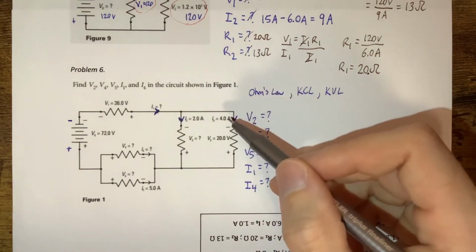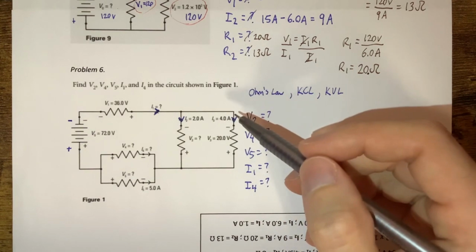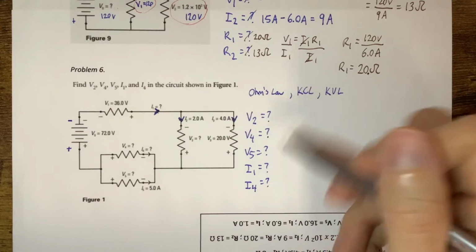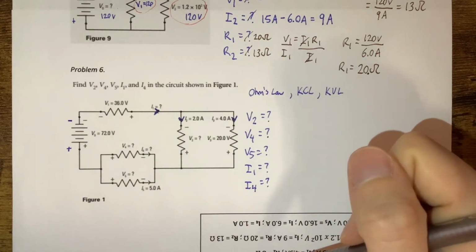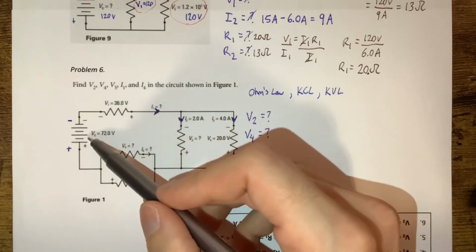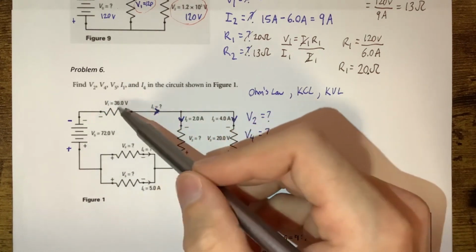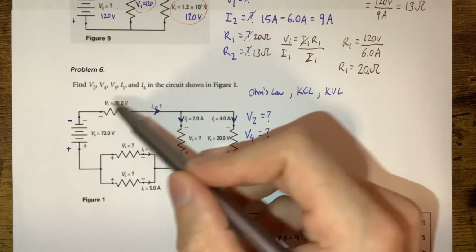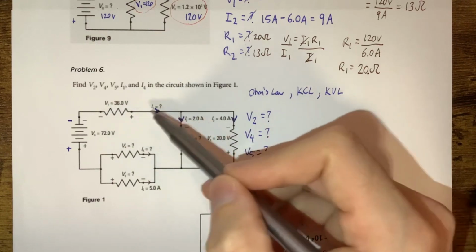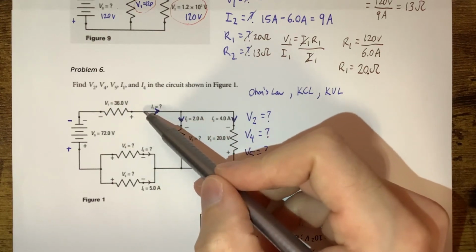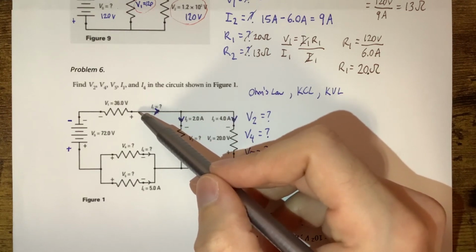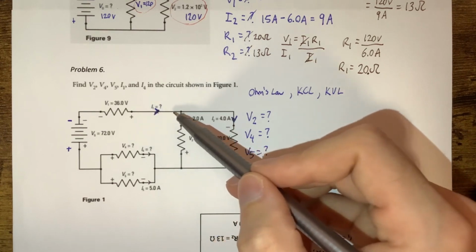So let's actually focus on the voltage. Let's do our voltage first. Why not? Since it's coming first, then we can always do current later, okay? So if we have 72 here, so we have 72.0, we're using up volts over this resistor here. So we used up 36 across this. So what are we left with over here, right? We're left with 36 at this point. So we got 36, these electrons are at that 36 volts and coming around here.